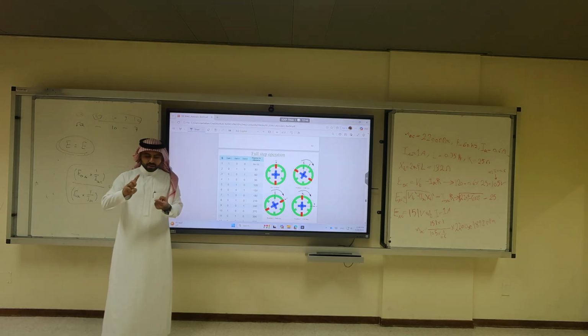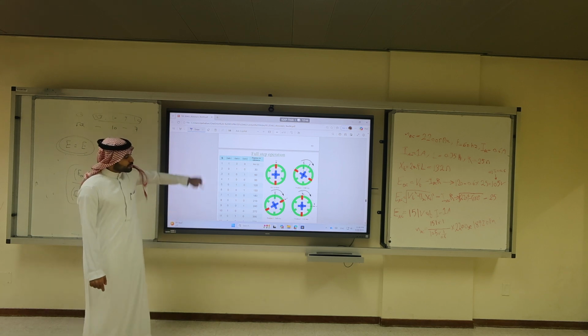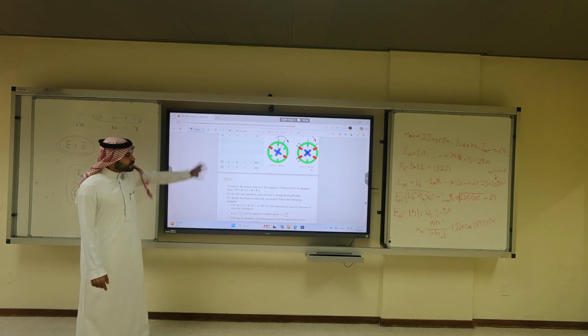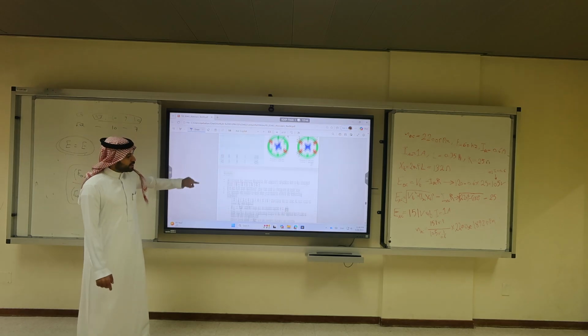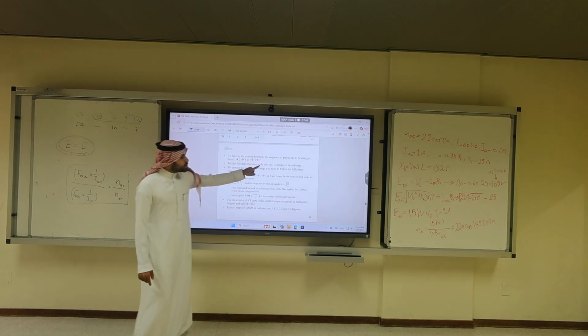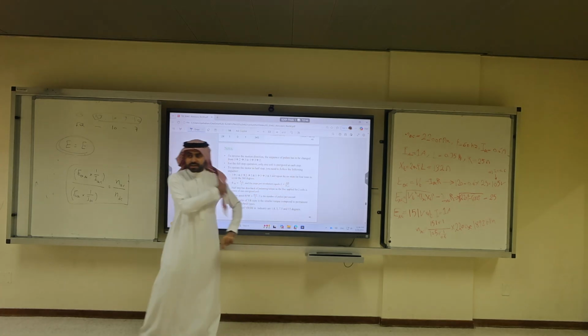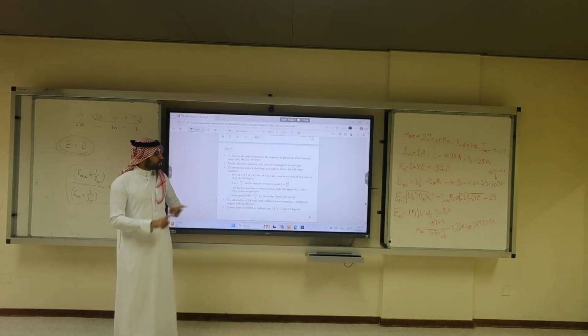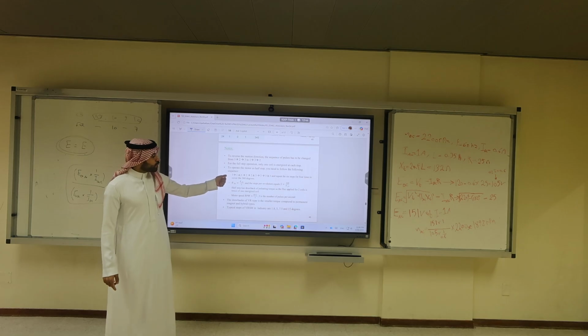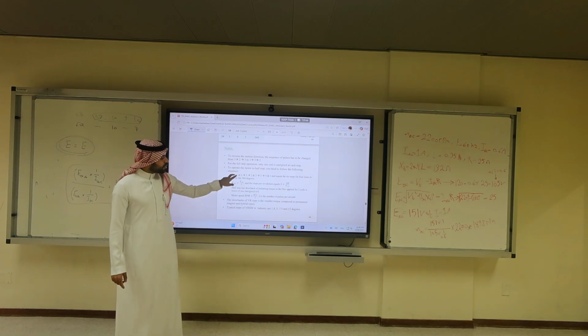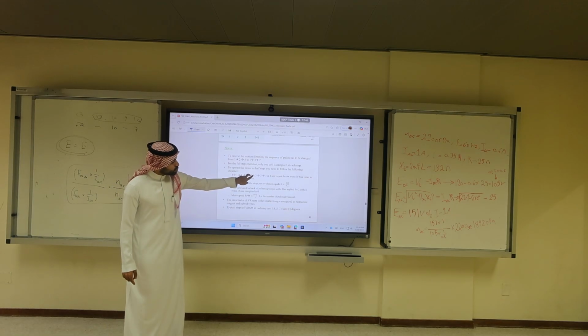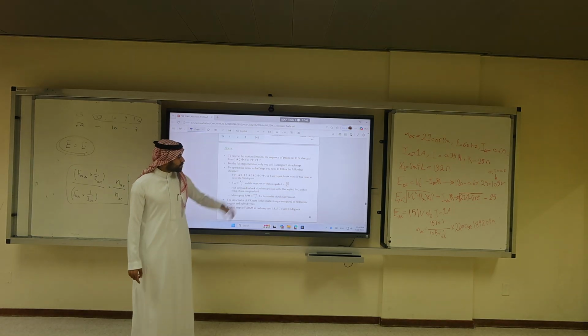So we have reverse operation, double coil full step operation, half step operation, and full step operation. The floor is yours depending on the tables. Do not memorize the tables, understand them. For the full step operation, only one coil is energized at each step. To operate in half a step, we follow this sequence: 1, then 1 and 2, then 2, then 2 and 3, then 3, and so on.